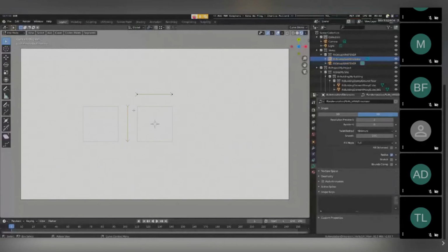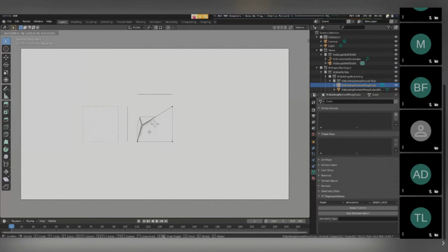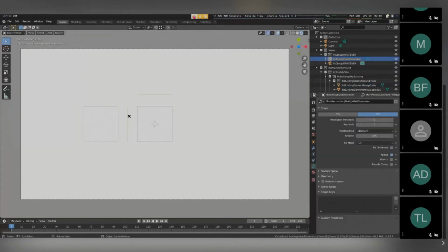And those annotations at the moment are not smart annotations. So if I move this, for example, the annotation does not move with it. And so it's very tedious for a big project and impractical, I would say. But again, this is something that's currently being worked on so that if you move one, the other one moves with it. And there's smart ways to associate annotations.